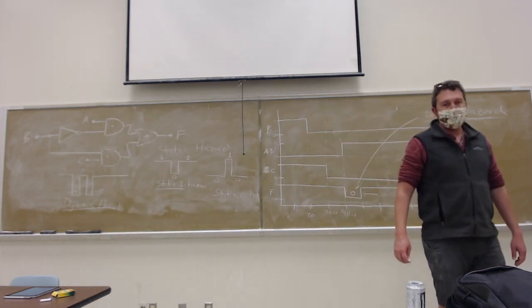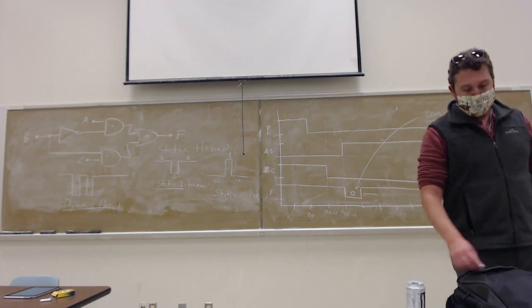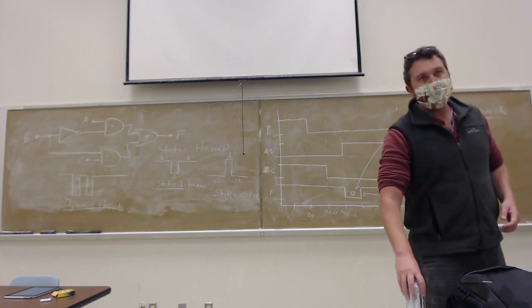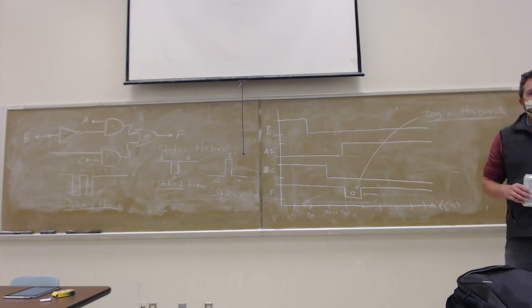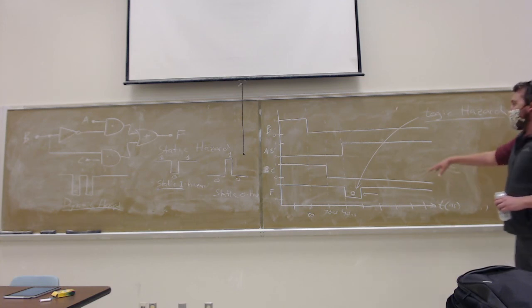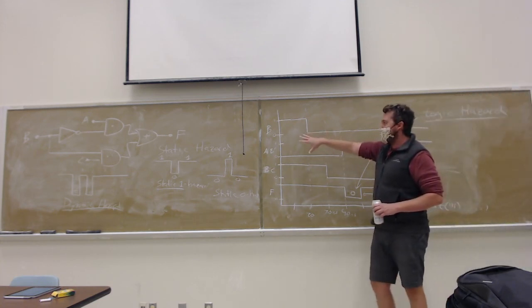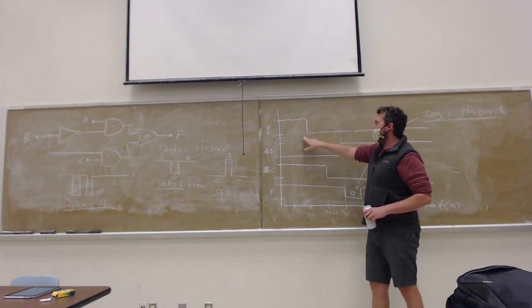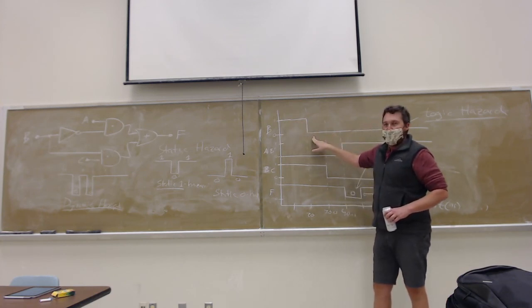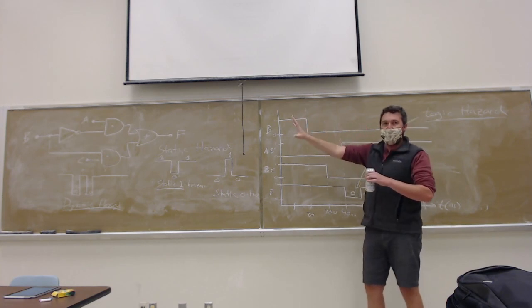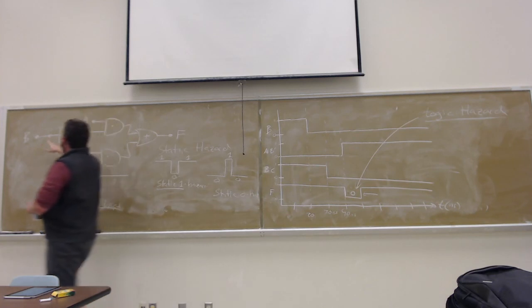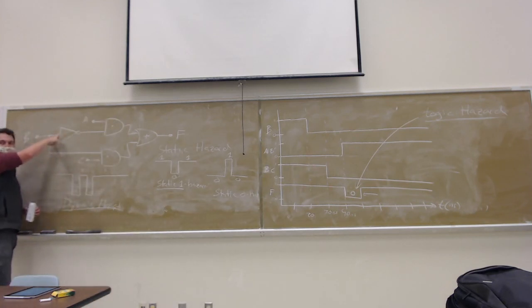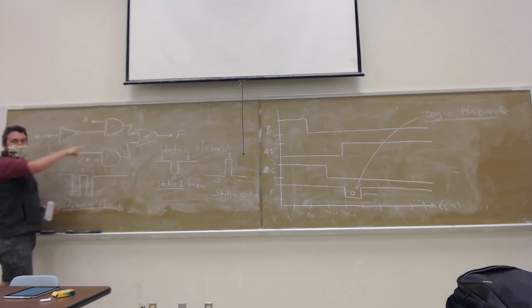What I was trying to ask was, so propagation delays, let's say the propagation delay is 20, so every 20 nanoseconds it goes from 0 to 1 or 1 to 0, is that how that works? Only if the input signals change. Right, so these only occurred in response, so everything was the same, and we had B equal to 1, but we changed to B equals 0, right? And because the signal takes time to propagate through the logic gates, every time your signal hits a gate, you've got to stop and wait 10 nanoseconds before you can move on to the next one, right?